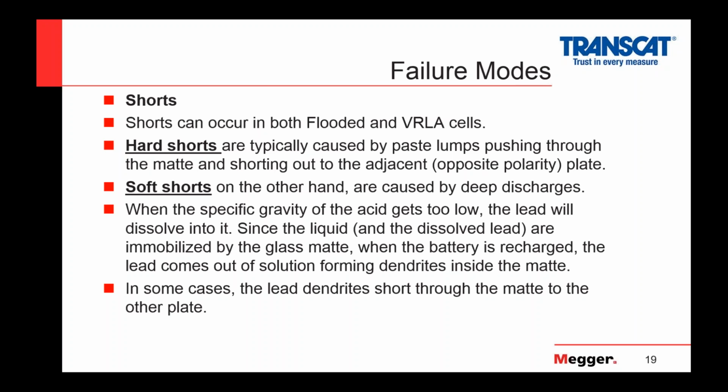And now when you go to recharge the battery, okay, some of it may go back onto the plates, but it won't go back in the same place on VLA batteries, and in VRLA batteries it gets trapped in the separators, and it creates what we call dendrites. The dendrites can short the plates out, and we'll see this as a drop in voltage and a drop in impedance.